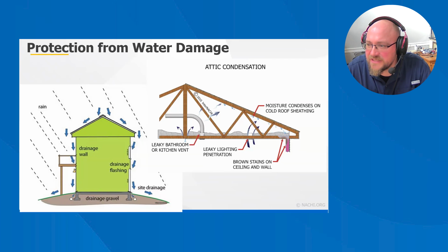And then water intrusion that's not so obvious. Water damage that is visible during an inspection should be reported to your client. It is not possible to see what happens to the attic space during the winter if you're inspecting the property during the summer, as in my case. There are a lot of things that are beyond the scope of a typical home inspection, including determining how moisture is controlled in the house, especially at the wall assemblies.